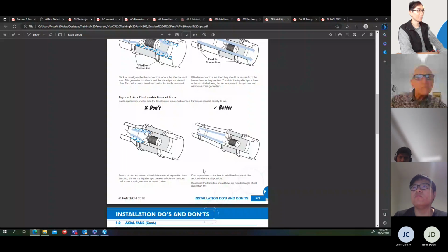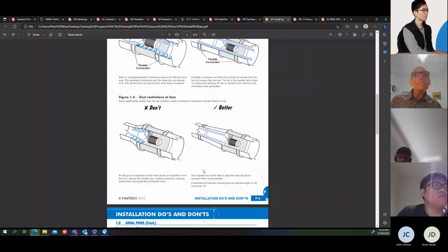Okay, well, yes, the advantage with slower speed is your fan will normally be smaller. That's one. You will sometimes get a better fan curve with a 2-pole fan. There's nothing wrong with a 2-pole fan. People used to say, "Oh, I don't use 2-pole because they're traveling at a higher speed, they're not going to last as long." That's not true. They're going to have the same life.